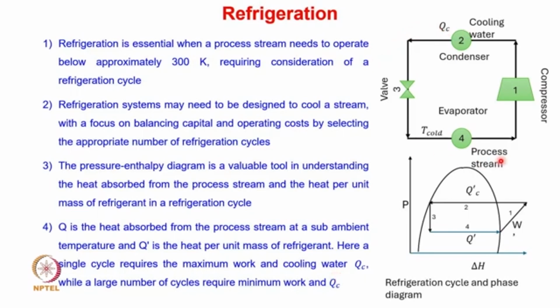So you can see that the refrigeration cycle involves four stages. The first stage is we compress the gas, isn't it? Then after the compressor, the gas is cooled in the second stage. Then the throttling takes place, where a valve is there and the throttling process happens, and in the fourth stage evaporation takes place. So with these four stages the refrigeration is performed.